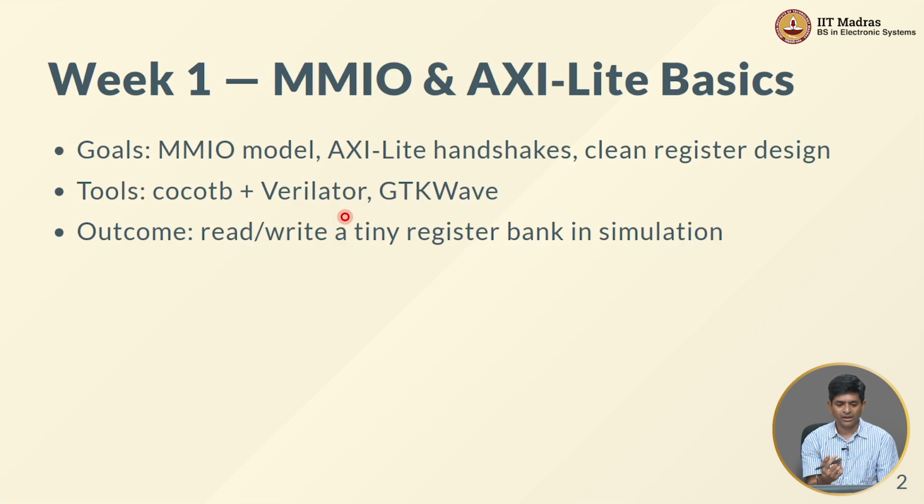So, Cocotb brings this notion of time and a clock into the Python libraries that we are going to use and thereby enables it to talk to a custom module that we are writing in Verilog and basically drive it, make it move forward in time and verify that the functionality is correct. So, I will be showing a demo of how all of that works and using that in order to explain the different concepts involved in the implementation of the registers.